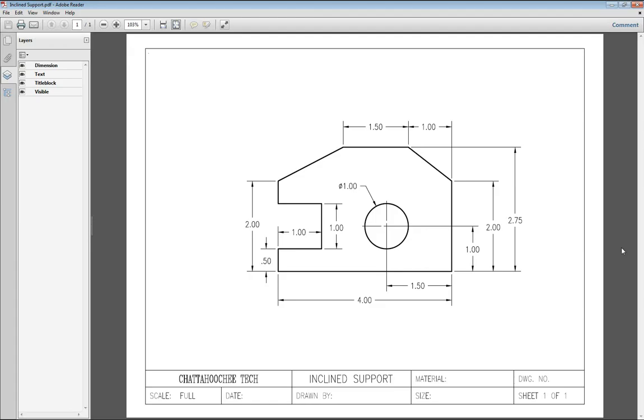In a previous video, I discussed how we were able to accurately reproduce these angled lines that you see here simply because we knew some linear dimensions, and we simply connected the endpoints of the angled lines to the existing lines. So that's one way to accurately reproduce angled lines, but you won't always have the benefit of being able to connect angled lines to the endpoints of existing lines.